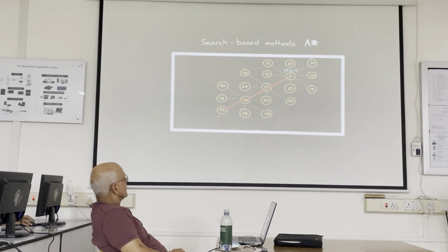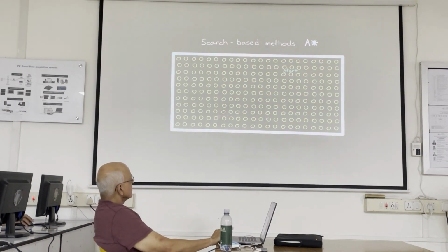Alright, so search-based algorithms give us a way to build up a tree by adding nodes in some kind of an ordered pattern. But one problem with these types of algorithms, even efficient ones like A*, is that they become very computationally expensive as the size and dimensions of the state space increases. You can imagine how the number of grid points grow exponentially as the number of dimensions increase, which can slow everything down. So they tend to not be used for high-dimensional state spaces, things like determining the path for multi-jointed robot manipulators, or for really large, low-dimensional state spaces.